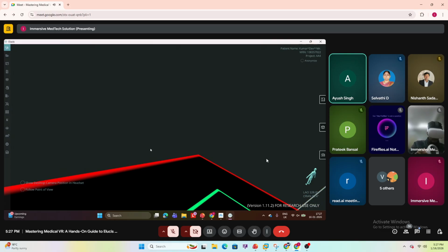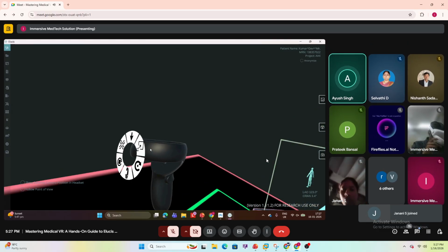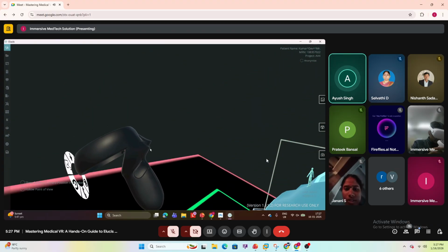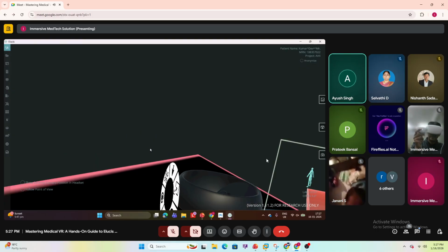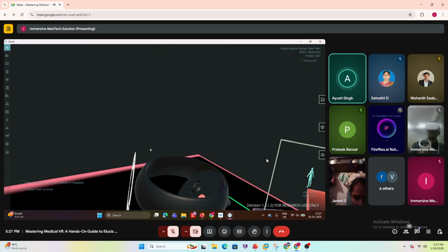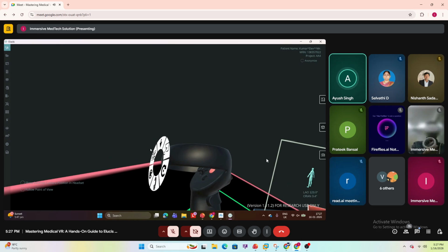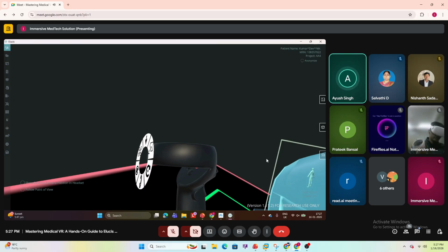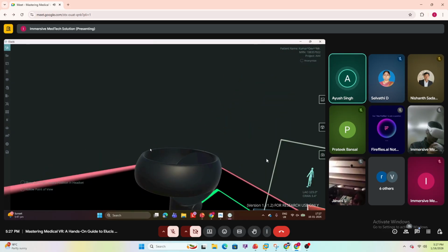So the dimensions can be set over here and any surface can be created. This is a very primitive size of a rectangle prism. Any other cylindrical structure can be created, and height and width can be changed simultaneously. Any surface can be marked up. For example, if we need to design a stent from scratch, we can click on a cylindrical surface and hollow it out. We can apply the particular designing pattern, whichever is required, the lattice pattern. Once it is done, we can convert it to the following points.